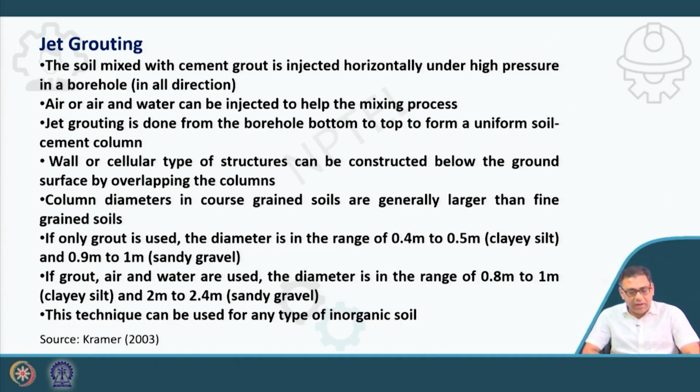Okay, air and water can be injected to help the mixing process. Jet grouting is done from the borehole bottom to top to form a uniform soil cement column. Okay, so now when this is horizontally injected in the borehole, it starts from the bottom and goes to the top to form a uniform soil cement column.